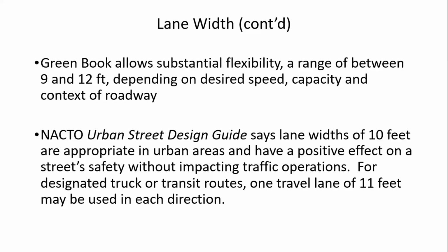NACTO has the Urban Street Design Guide, which talks about lane widths of 10 feet as appropriate in urban areas, and these can have a positive effect on safety without impacting traffic operations. They do note that for designated truck or transit routes, one travel lane that's 11 feet wide may be used in each direction.